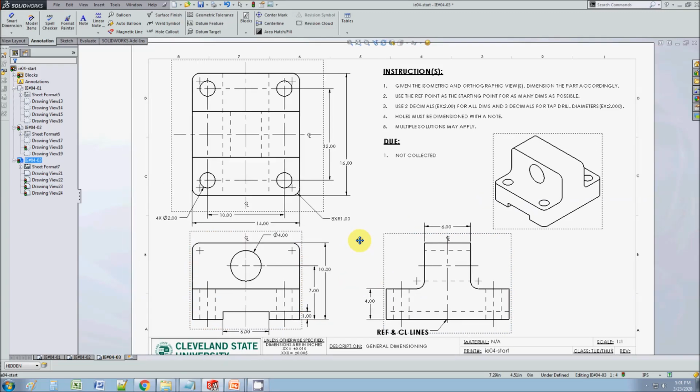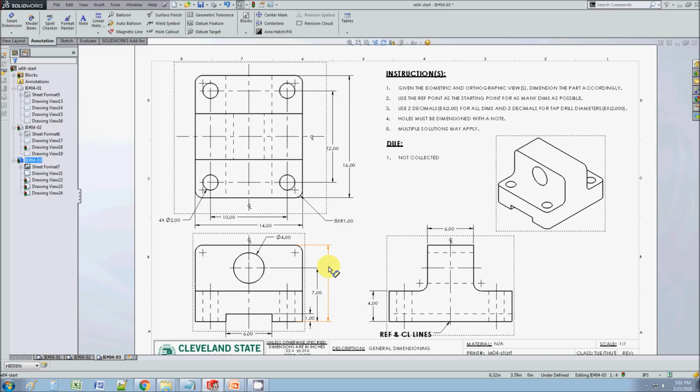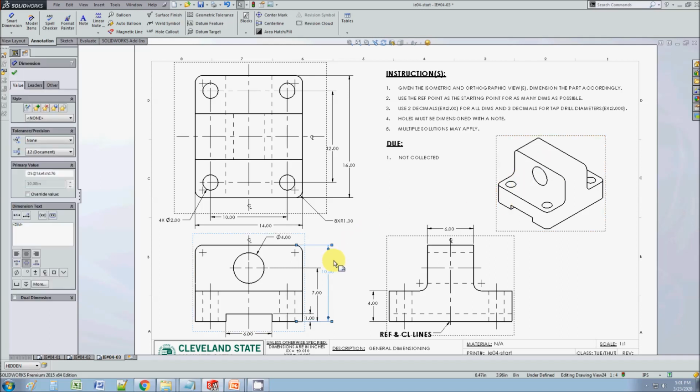Okay, so let's see if we have any duplicated or missing dimensions. I need to machine this. Let's say we're milling this. We're going to need the height, the width, and the length. All right, so we've got the cube. Then we have some sort of notch that's this wide. We already know where the center is. We're going to center on our end mill, go this wide, go this high, and then with the hidden lines here, we're going to cut all of that in one shot. It's going to be a through cut.